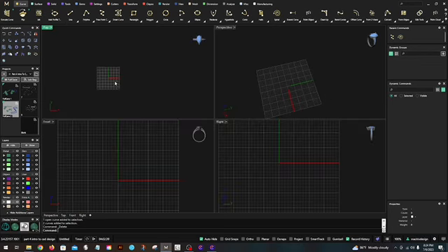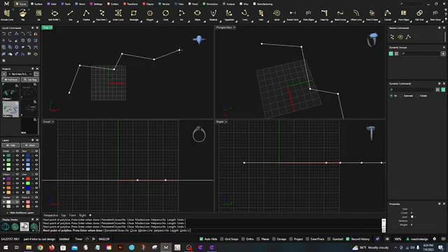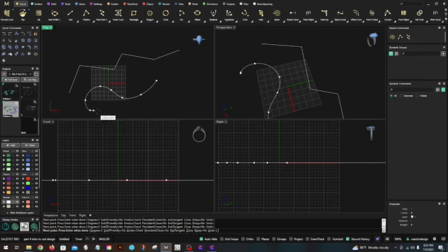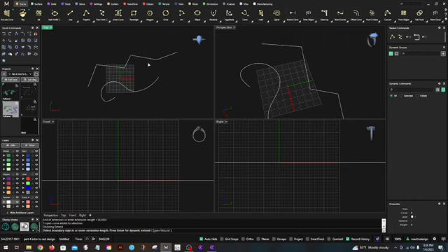All right, I'm going to bring in a couple lines here, practice our little polyline, and we're going to do a freeform curve. All right, extend curve, and select boundary objects. I'm going to enter that. And then you click on the curve again.